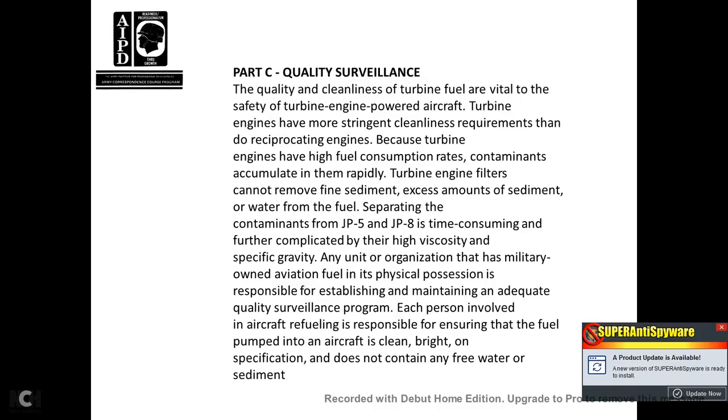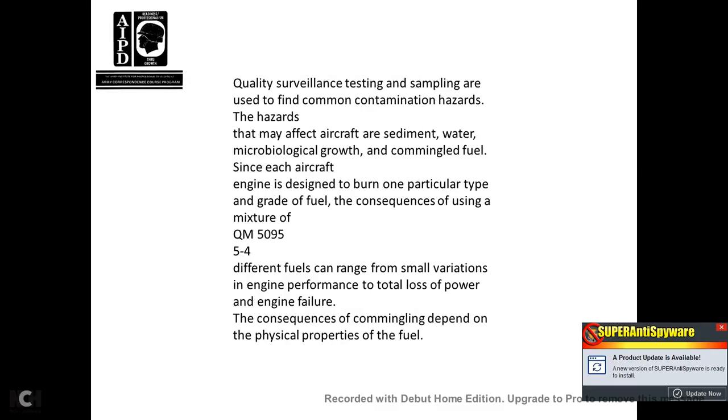Engine filters cannot remove fine sediment. Excessive amounts of sediment and water in fuel, and separating the contaminants of JP5 and JP8, is time-consuming. Further, they are complicated by high viscosity and specific gravity. The unit organization, military-owned aviation fuel, and physical position responsibility establish and maintain an adequate quality surveillance program. Each person involved with aircraft refueling is responsible for ensuring the fuel pumped into the aircraft is clean and bright, and meets specification without free water or sediment.